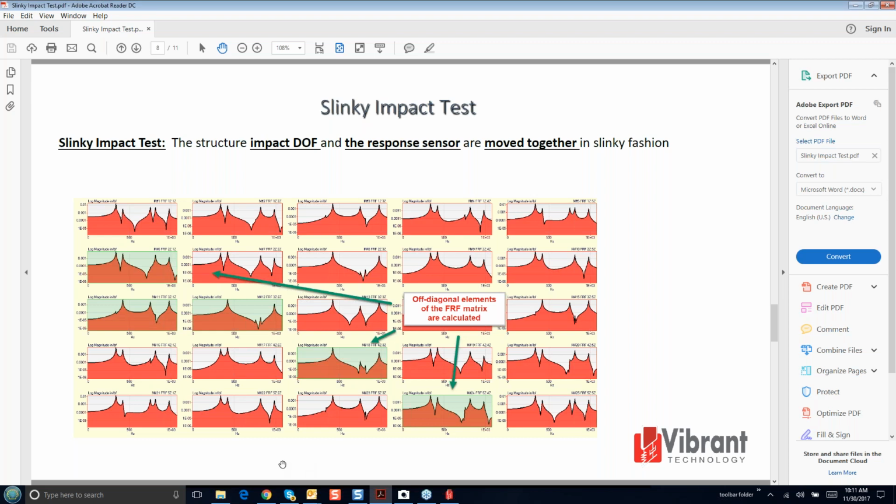This is a device made by a company called GTI Spindle, and it's a rather new wireless device, and it's a two-channel device. So in order to make these cross-channel measurements, we need to have a two-channel, either a portable data collector wired to a hammer and an accelerometer, or in this case, we're going to demonstrate the use of the GTI with a hammer and a wireless accelerometer, and the signal is wirelessly going to the computer, my computer here, and we'll show you an impact on a structure.